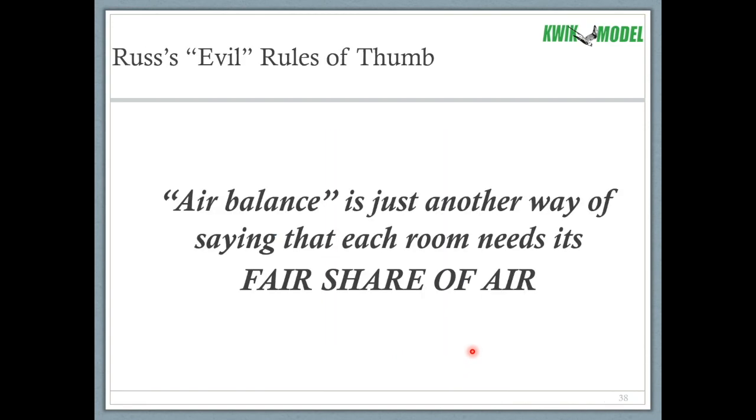Another rule of thumb: you hear the term air balance a lot. Oh, this house has bad air balance, or we need to do air balance on the system. Well, air balance is just another way of saying that each room needs its fair share of air. Fair share of air means that each room needs an amount of air that's proportional to that room's load. In other words, if a room has twice as much load as another room, it should get twice as much air. If a room is 10% of the total load, it needs 10% of the total air.